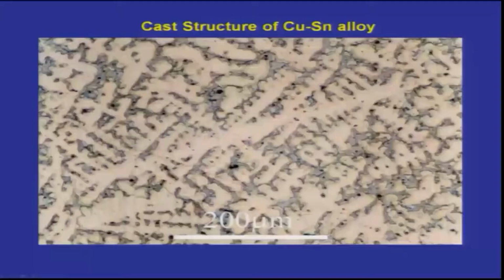as I told you. This one is copper tin, which is a bronze, and as you see here, these are the dendritic structures which are revealed. There is some other phase, beta, present, and the yellowish colored phase is the dendritic phase, and you can look at some of these places and see the dendritic structure develop. You can see here this is what the dendrites are, everywhere, and in between two dendritic arms something else has formed. That is why it is a little bit cumbersome to observe, but you can make it out this way. Okay, that is what a dendrite is.